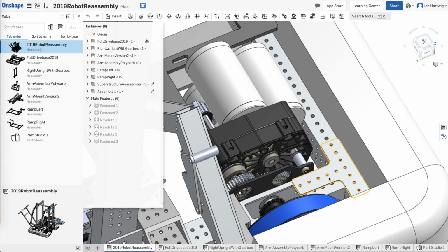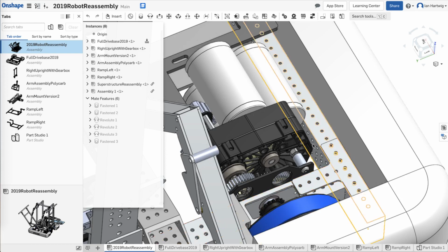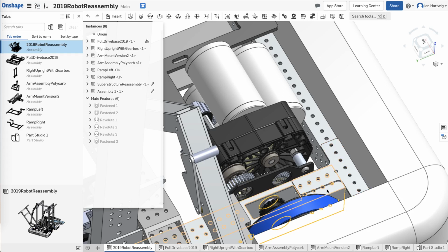You can see that we try to have 4 holes here in each direction. But the fun part is that our drive tubes are actually, instead of being 1 inch wide like the front, 1.5 inches. So they have twice as many holes. So let's make a bracket that's specific to this double width hole pattern.